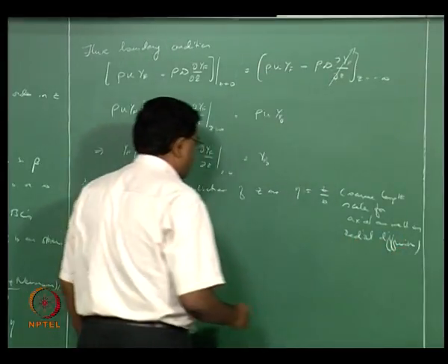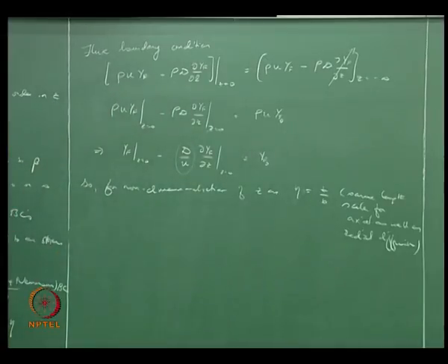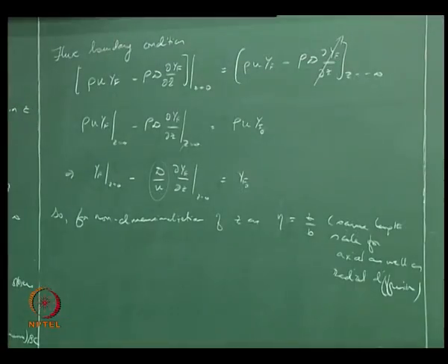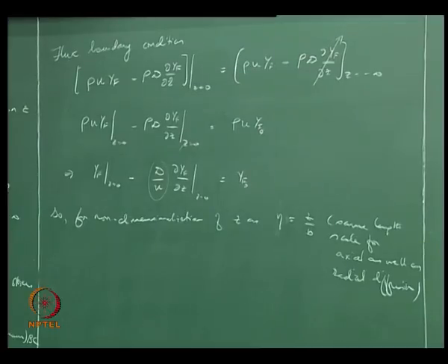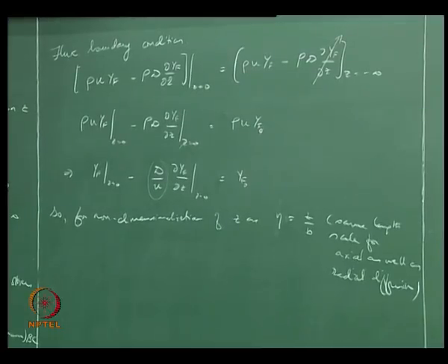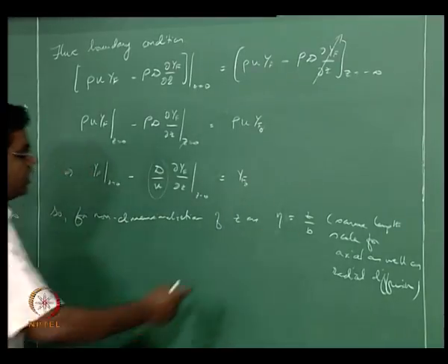This was not the case before. We didn't have an axial diffusion length scale unless we actually started looking at what is the flow versus the diffusion length scale. So we had to do something like z by b divided by u by b squared by d, and then we came up with a new non-dimensional coordinate, eta, last time.